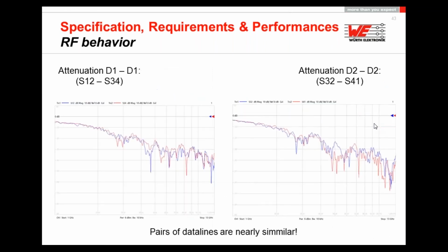And then we have to analyze, of course, the crosstalk also by the changing frequency. How does it affect the other lines? And all these data, a good connector manufacturer will be able to provide to you as real measured data.